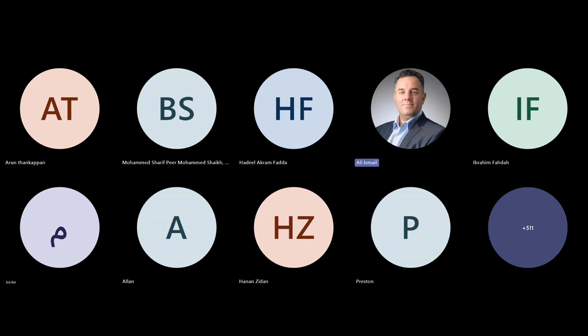But in most cases, I think it is a wise idea to check and analyze the IFC model before submitting to the Build into Pay platform, using any desktop viewer like BIMcollab Zoom, BIM Vision or Solibri. There are many available free tools which allow you to check if your model is exported correctly.